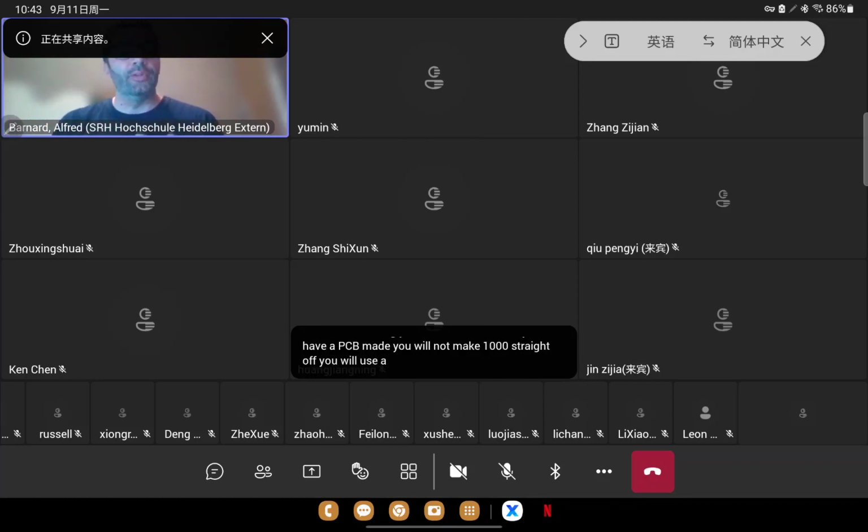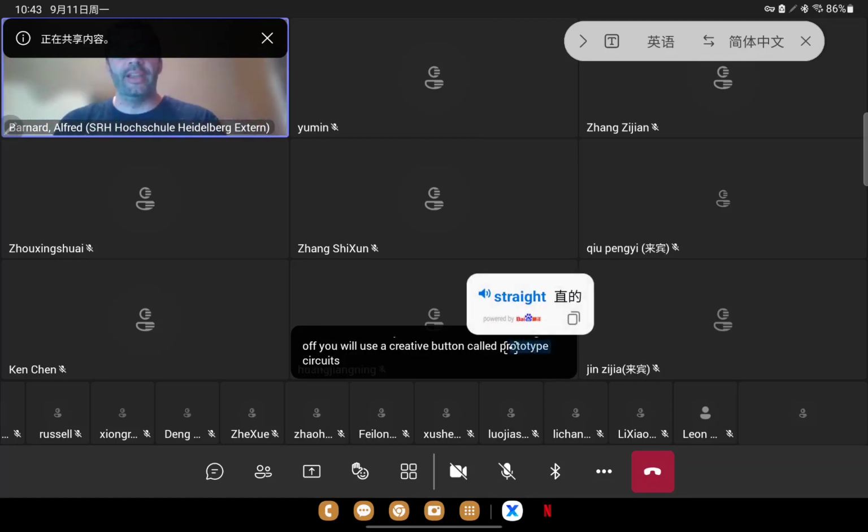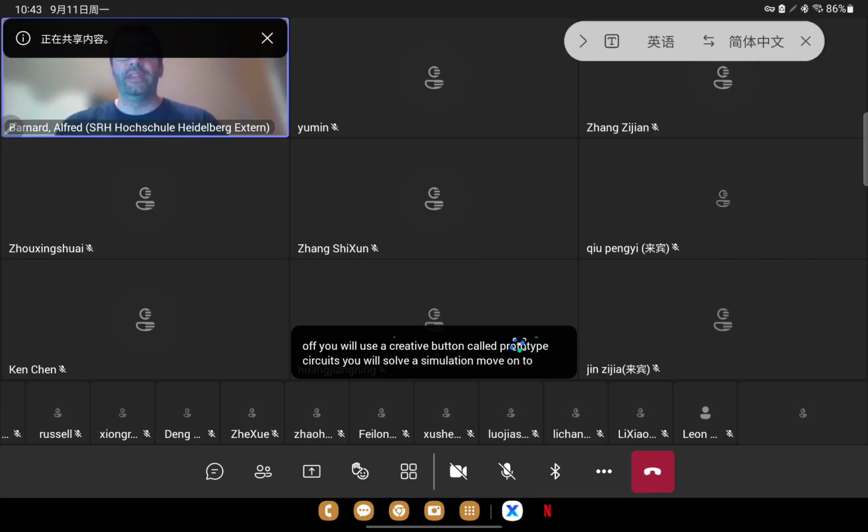You will create what we call prototype circuits. You'll start with simulation, move on to breadboard, then maybe a strip board or a Vero board, and then to PCB, and then you'll test that board. You'll perform certain tests under certain loads to see how your board performs, taking physical readings, and then you'll have to inspect your board like we're going to be doing here under a very, very simple microscope, which I've been trying to get working for quite a while now, and it finally does.